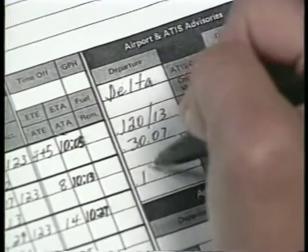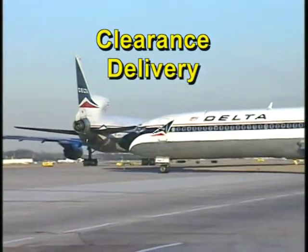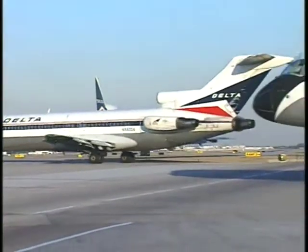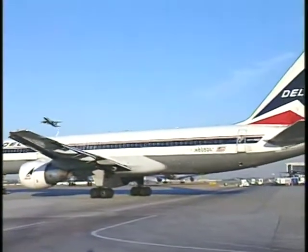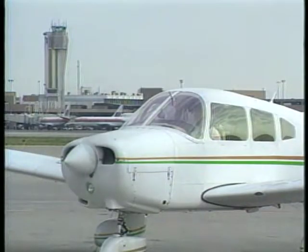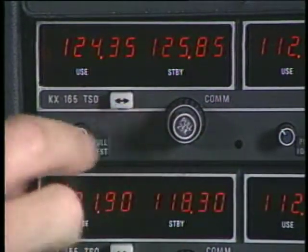Advise the controller on initial contact you have information Delta. Airports with a high volume of traffic may have a position called clearance delivery. It's primarily an IFR service, but can be used by VFR pilots to help improve the coordination of departing traffic. The controller provides you with a heading, altitude, transponder code, and departure control frequency to use after takeoff. If you want to use clearance delivery, contact the controller after listening to ATIS and before calling ground control. Inform the controller of your aircraft type, direction of flight, and that you have listened to the ATIS information.